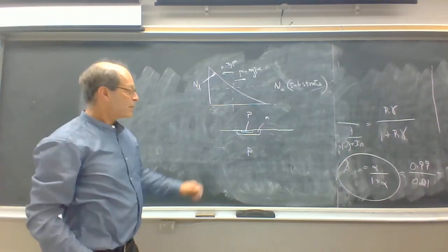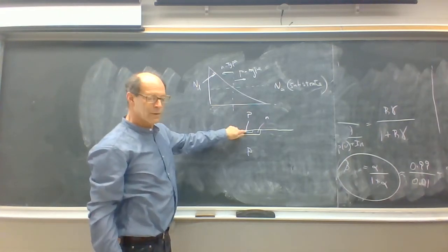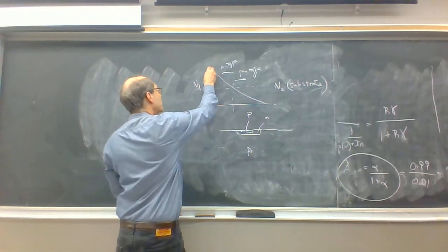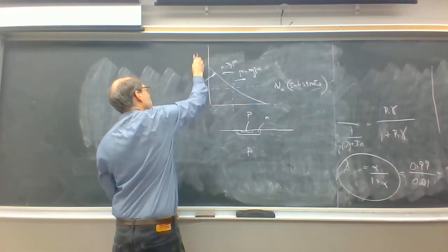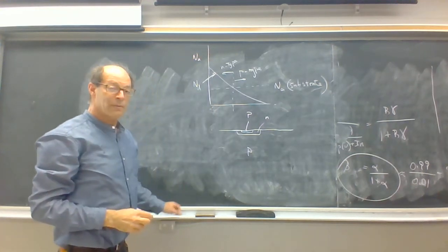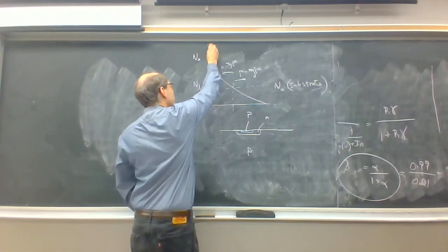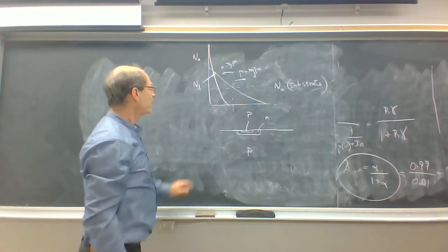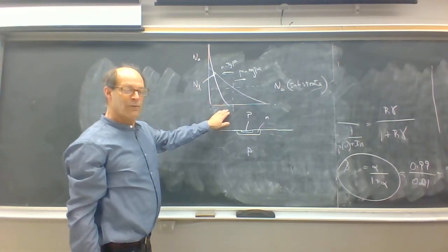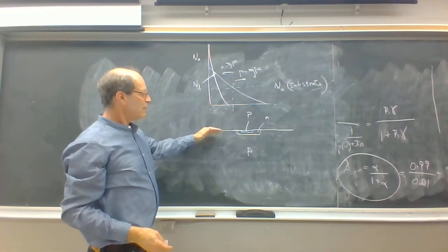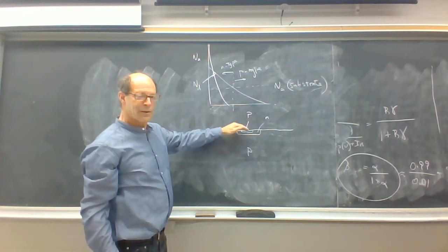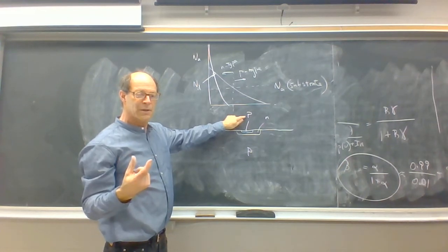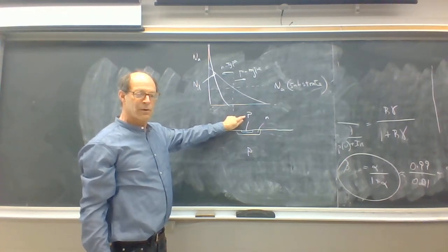Then after this doping is complete, we introduce this second p-type layer. So we're now going to introduce an acceptor doping again, but only near the surface. So we have a very high concentration of acceptors near the surface, which falls off according to the doping profile. In principle, we would reduce the diffusion length in the p-type doping by reducing the length of time and/or the temperature of the diffusion of these impurities.